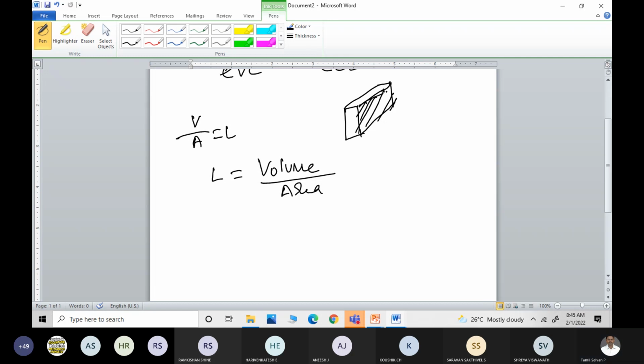See, I am talking about the lumped parameter system. Don't think of one dimensional heat transfer. In a lumped parameter system, the whole body is dropped inside, so heat is transferred from this side as well as the other side. You may ask, sir, even on this surface the heat is transferred, but the heat transferred in this area is negligible when compared to the two sides.